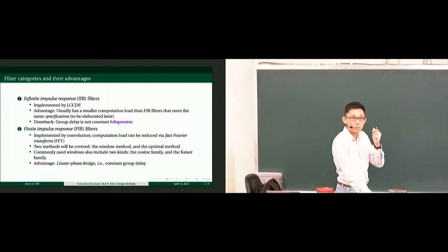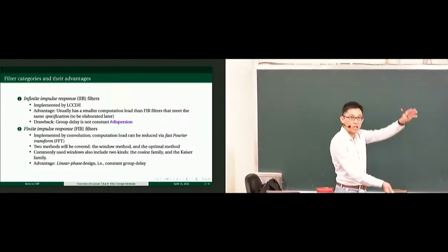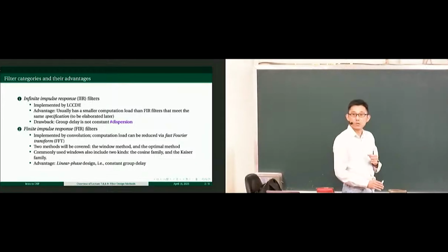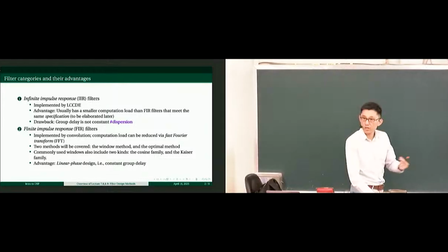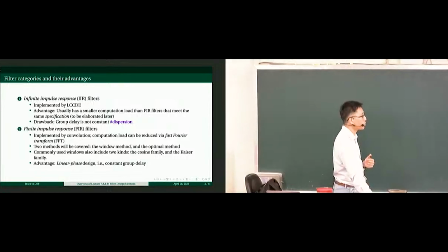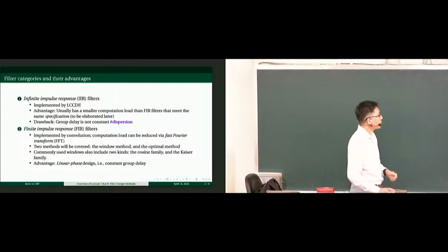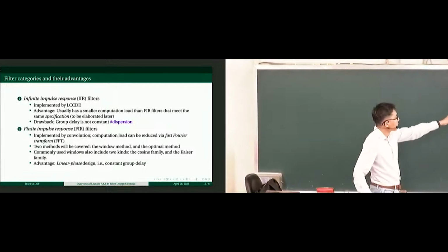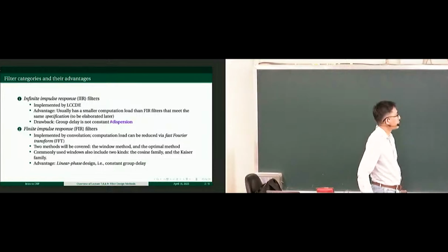A filter makes a multiplication in the frequency domain so that you are giving your signal a gain as a function of frequency, and a phase shift, because everything is complex valued. Those are complex numbers. With that, we will learn two main categories of filters.